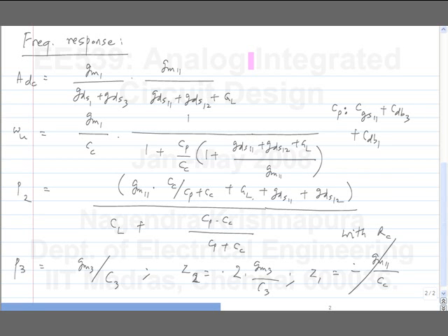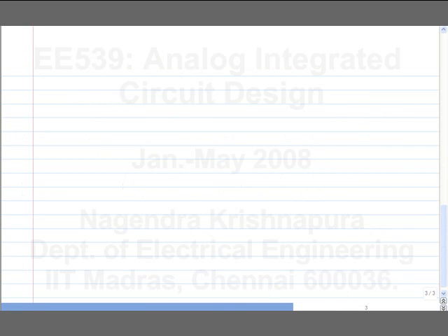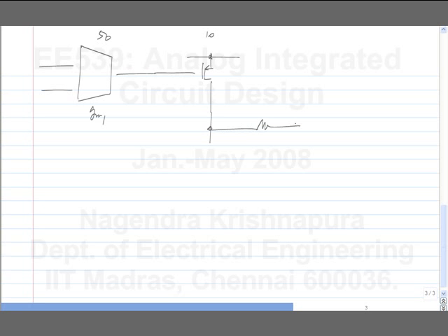If I choose to use exactly the same first stage, so this is exactly what you have designed, perhaps a scaled version of it, meaning you scale all the widths and also the bias currents. If you do that, the DC gain doesn't change, right? Then I connect it to a second stage. Now this provides a gain of 50, this provides a gain of 10. Now a gain of 10 is probably still too much for a second stage, but let's assume that we have done it.